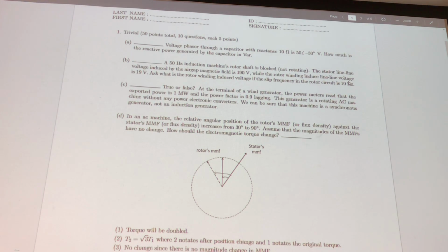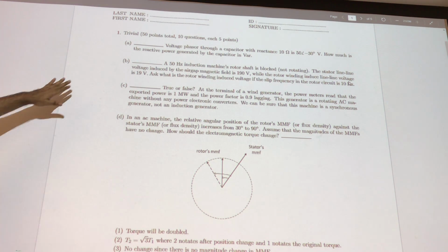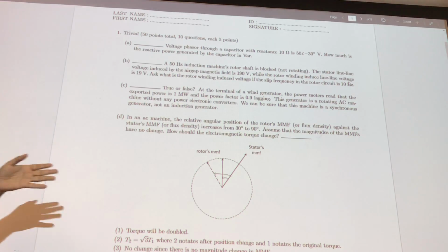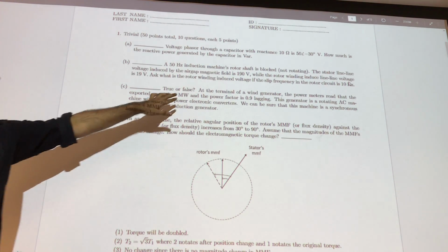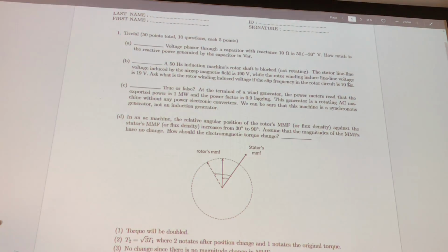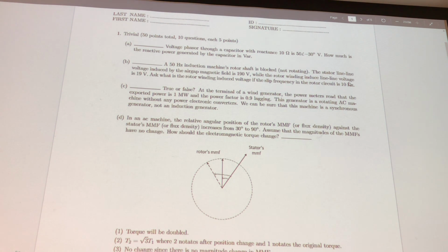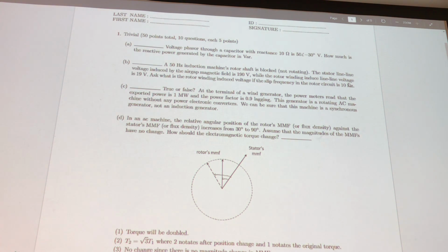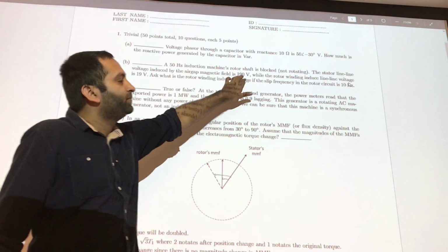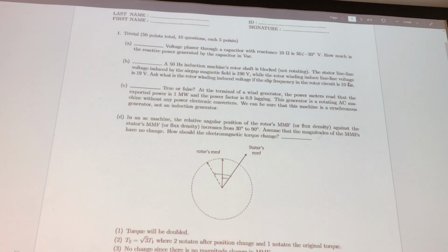So you have to remember one thing. It is not important for this question, but for the other big questions: whenever you are looking at the voltage given in the question, that's always line to line RMS. But when you are solving the equivalent circuit in an induction motor, it's always per phase. So whatever voltage is given, you have to change it to per phase, by dividing by square root of 3. Remember that, because that is one mistake most of us make, we forget it.